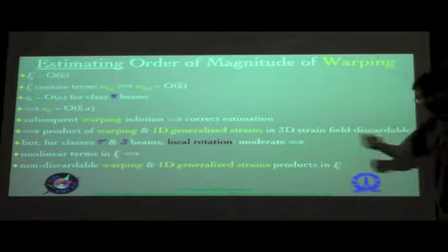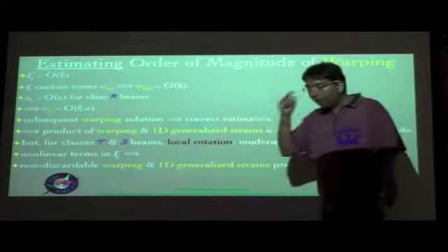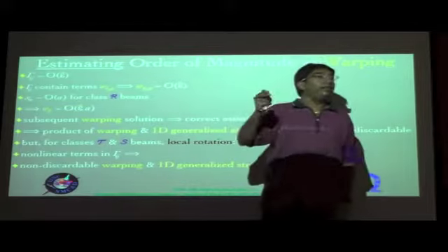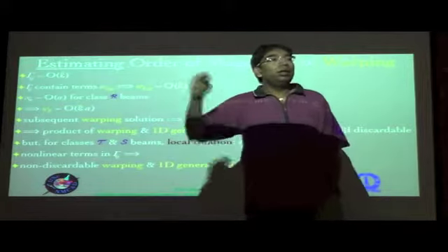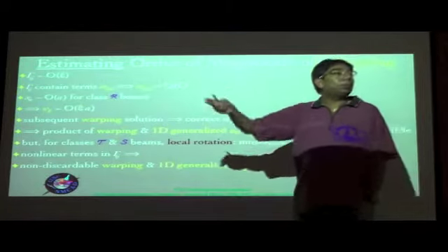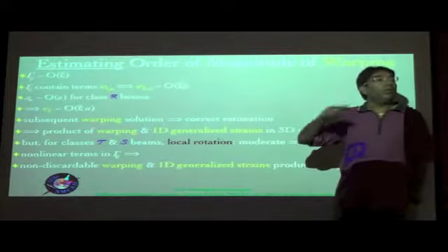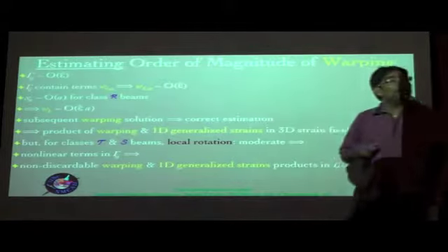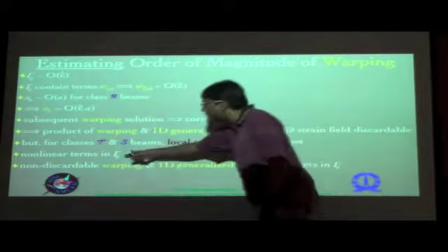We saw in the expression for gamma ij, we had a leading term which was eij, and then you had terms like phi tilde squared, and terms for phi tilde multiplying e. So it's quite obvious that all of these will involve products of the unknown quantities and therefore nonlinear terms in gamma ij, that is in the 3D strain.